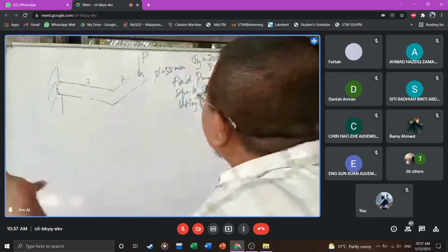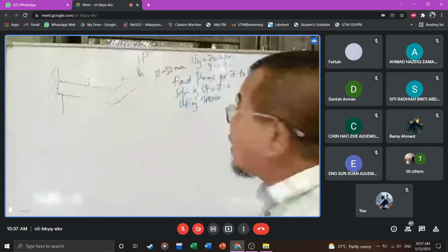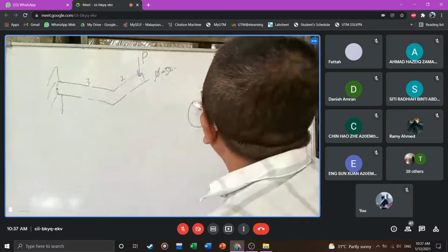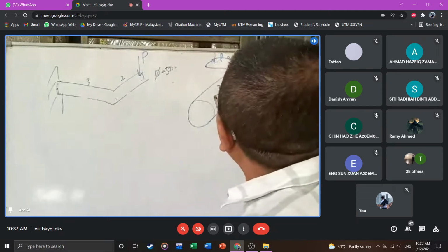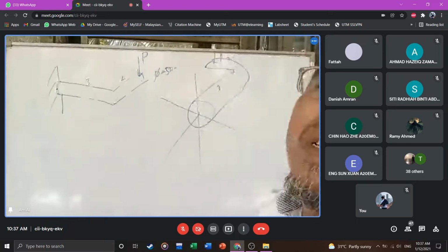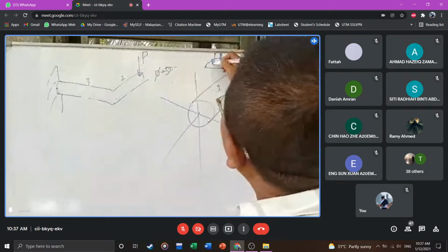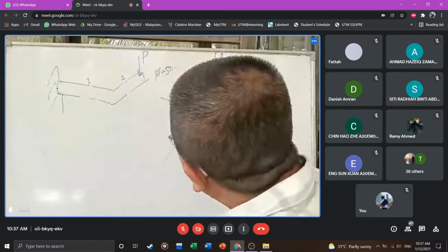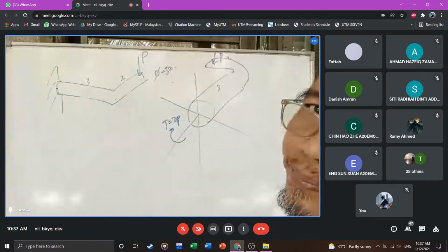I draw the other side diagram. Yeah, draw the other side diagram. Same thing. P there, 2 and 3 there. I have to draw this diagram. Very important here. Cut from here and look from here. So P there times 2 is torsion there, rotating that way. So that must be a torsion there equal to 2P. You see that?